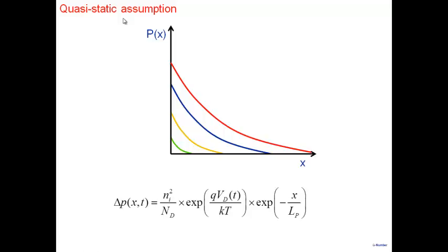Right? So we derive an expression for capacitance. Remember, how did we derive it? We say C equal to ∂Q/∂V. How did we get Q? We said we'll integrate p as a function of voltage. And where do we get p? We get p from the static case.